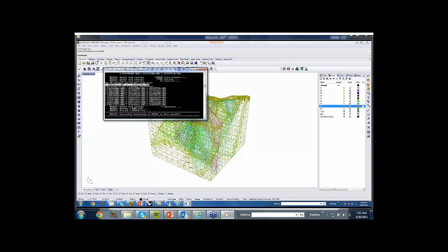So they become different face groups, which then later on essentially takes away any need for manipulating ranges with coordinate systems. So it reduces the size of the data file considerably and makes life very easy. But that information about where you're going to apply the boundary conditions, where's the east wall, where are the boundary conditions on which you put, say, hydrostatic, and those that are going to be on rollers or those that are going to be fixed, that information is already known in Rhino. We already know that.